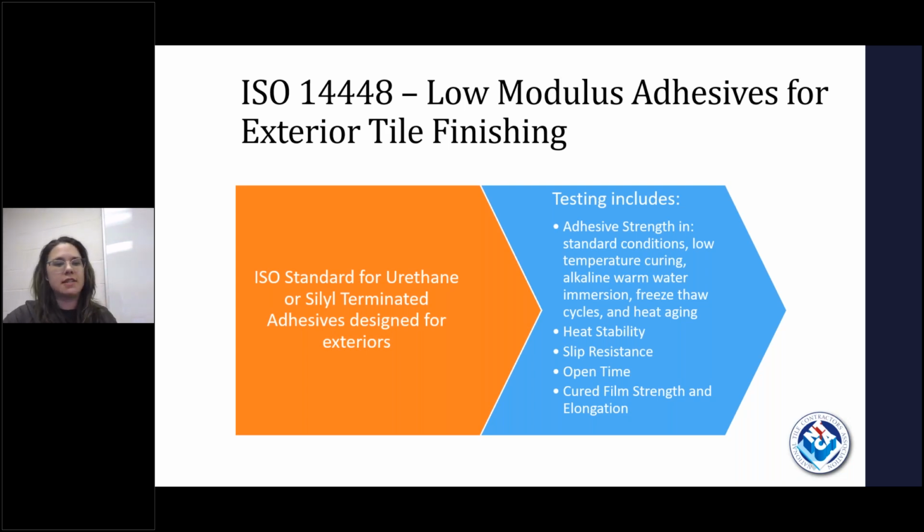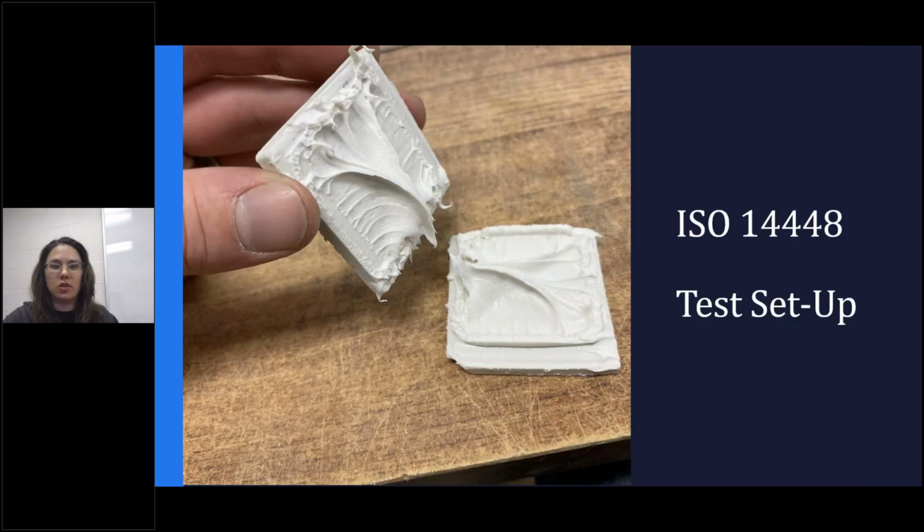Just to give you an idea, standard curing conditions are very similar to ANSI standards, right? You're going to be curing these things in 75-degree Fahrenheit temperatures with about a 50% relative humidity, for about 672 hours, give or take, right? But after that, things kind of start to get interesting, okay? I'm going to start by just showing you guys what some of this testing looks like.